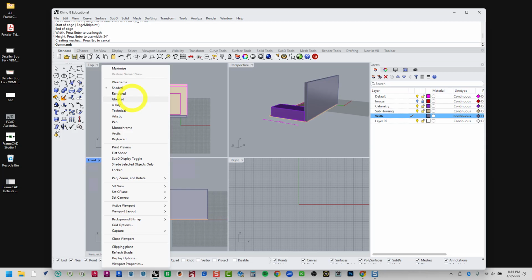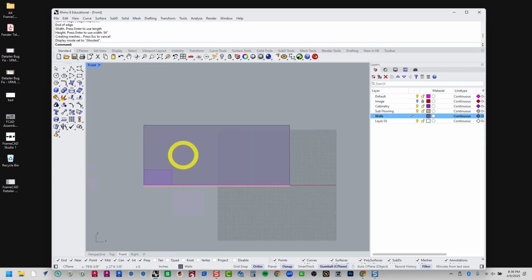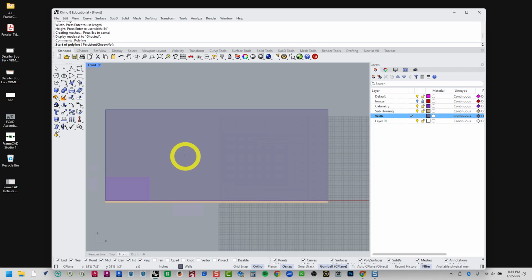And then I'm going to keep going with this polyline. I'm going to utilize this basic rectangular wall that I've drawn and draw upon it. And at this moment, I'm still kind of sketching. So maybe I want to do it to about here. Maybe I'm going to connect it to this edge over here. And I'll come straight down, go straight over here, and then close it up by clicking on that first point that I had already clicked.